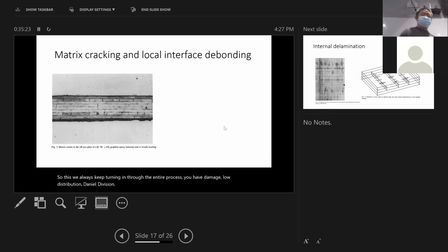And these are the early signs of cracks. You can observe these directly or using a technique called replica. There's a set of compounds you can mold to the side of the plates, because composite structures are sometimes huge and you don't get to carry them into an SEM. So you stick this replica compound on the side, harden it, take it back, and then use SEM to look at the replica. It gives you all the features. It tells you about all these cracks.